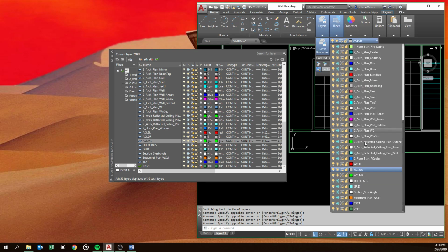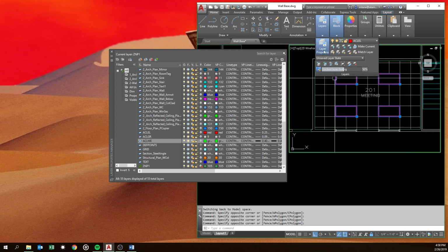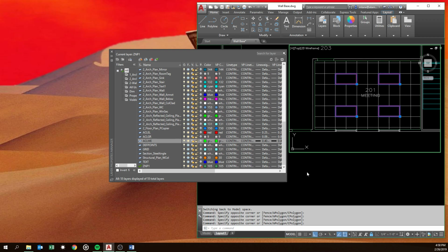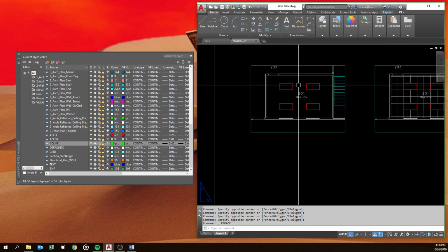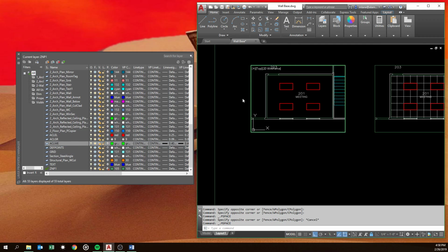Those blocks shouldn't be on the grid layer. They should be on the electrical layer. So let's put them on the layer that they're supposed to be on. Click back outside of the block. Get over here. You will now notice they're visible here. They shouldn't be. So if we come inside here on that little viewport thing, next to the normal freeze thaw,